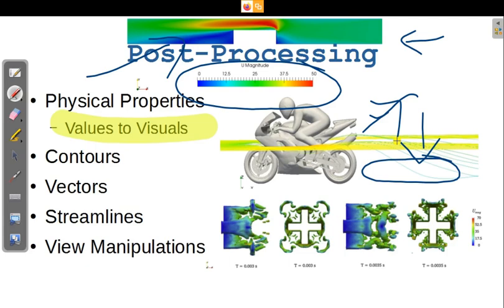The other aspect is shown on the bottom side. It's a transient flow field wherein I have done some post-processing called Q criterion. It's a derived post-processing wherein I created a utility in C++. I took the velocity flow field and mathematically manipulated the velocity data to calculate the velocity gradient tensor, and from the velocity gradient tensor you can derive the invariants. One of such invariants is taken and an ISO value of that is stitched into a contour, and you are seeing those blobs. These are exactly showing the vortices or vortical structures, or rotating masses of fluid elements.